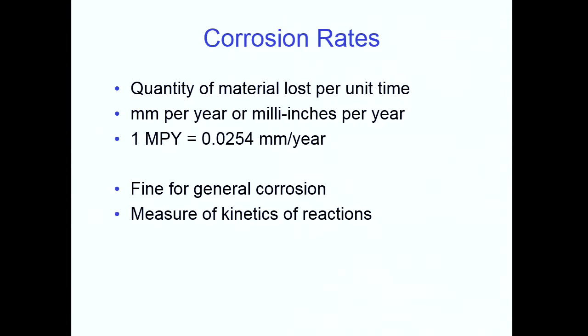So this was just to say that we were interested in loss of through-section thickness. Commercially, that's looked at in millimetres per year, or in the United States in milli-inches per year, and that sometimes causes confusion. So you've got to remember that there's a conversion factor here.